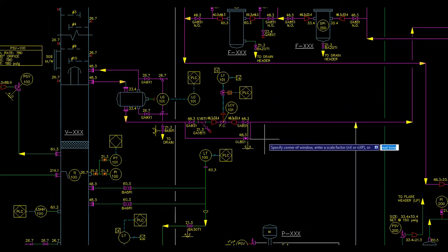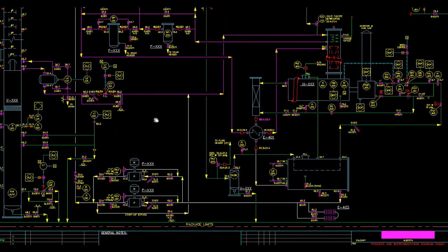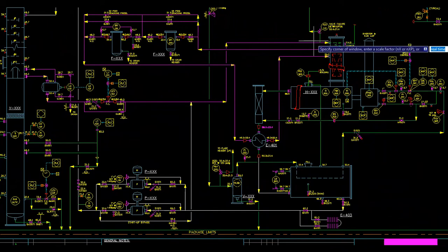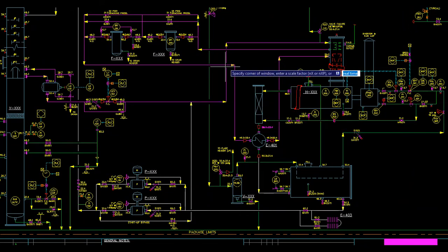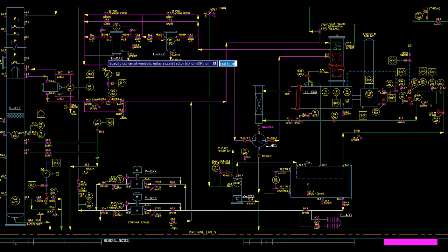Since the lean glycol is hot and rich glycol is cold, in the next units the objective is to exchange heat from one to another. If the rich glycol is heated a bit, it will reduce the burden on the reboiler. If the lean glycol is cooled, it will enhance the dehydration process. Therefore, it's a good idea to design the units in this way so that they are energy efficient.